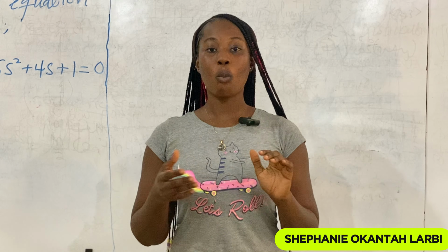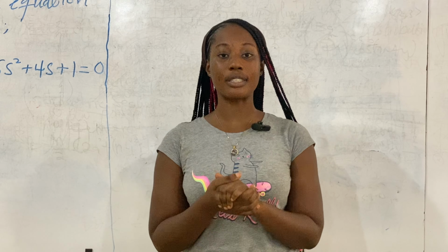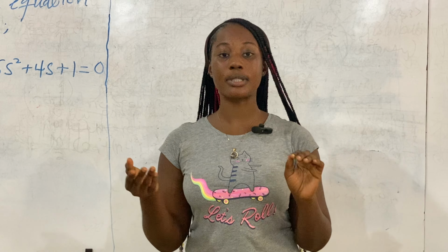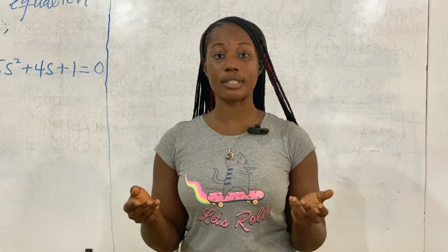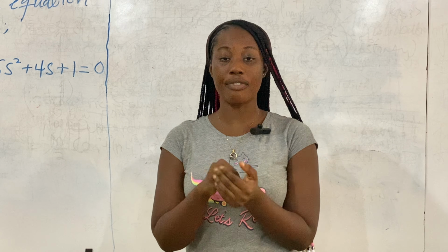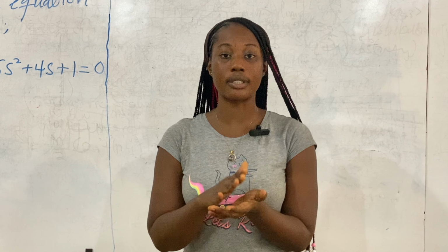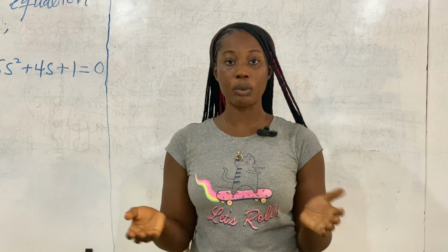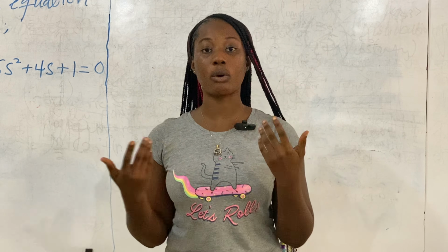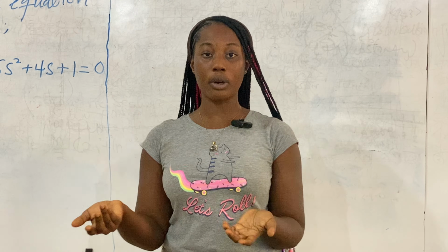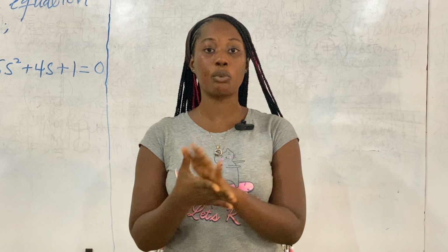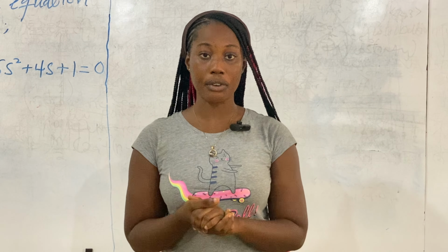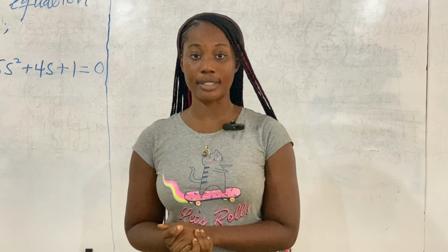In control systems, one of the most important questions engineers ask is: is the system stable or not? A stable system responds to input and eventually settles down, while an unstable system behaves unpredictably or can even fail. In this video, we will explain the concept of stability, its importance, and how to determine it using the Routh-Hurwitz criterion, followed by a step-by-step example.